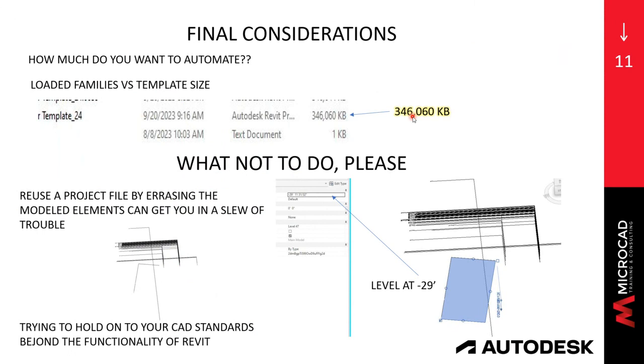So what families do you want to load into your template file? You want to load the families that you most commonly use. So in my BIMCAD manager workflow, my engineers would call me up and would just say, there is such and such family that I need in every project, and in every project I have to go to the library and load it.